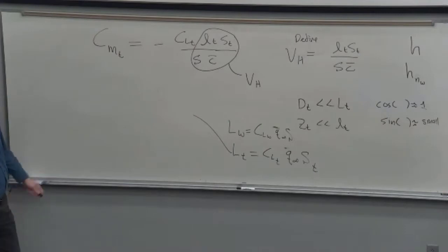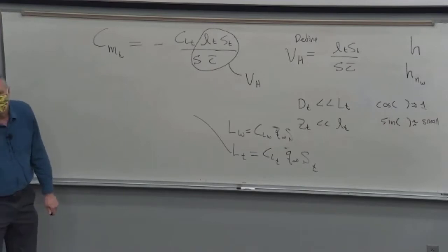Yeah, and that's what I was talking about. Sometimes you'll actually have to include the V prime squared if V prime is less. But typically we neglect that. So typically we can just use V infinity squared for dynamic pressure. It's an approximation, but it's usually pretty good.